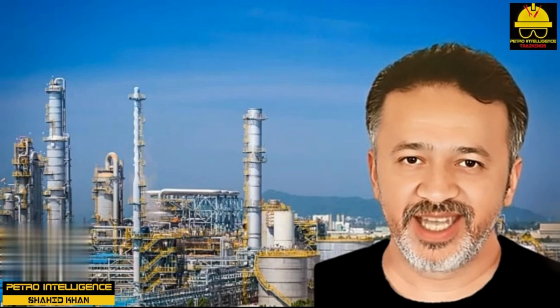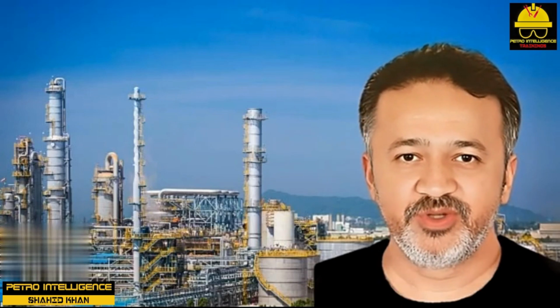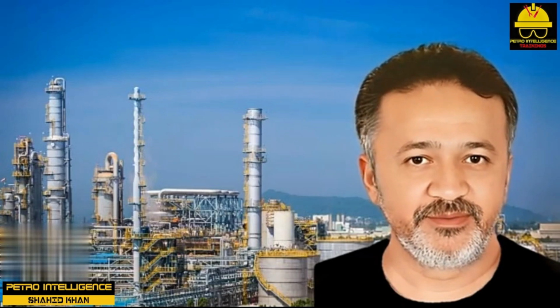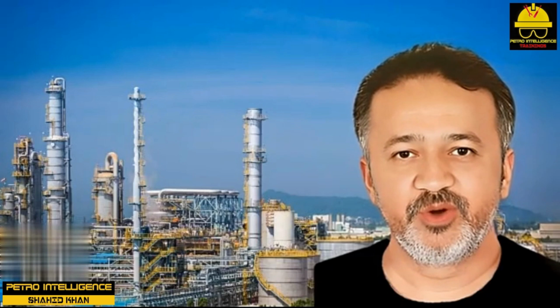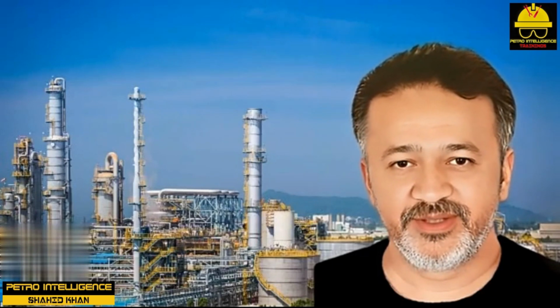The majority of the towers I work with have too many trays. Designing for extra trays is the designer's futile attempt to offset tray hydraulic problems described in this video. Tray inspection after installation or during a unit turnaround is a lot more important than the selection of the best tray efficiency calculation model. That's all, gentlemen.